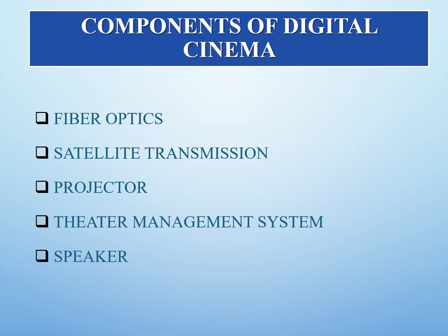Projector. Digital cinema projectors directly accept and play digital format images in high quality. DLP, digital light processing technology, is used to project images, while some of them might use LCD or some kind of modified LCD crystals for projection. Common projectors support 2K, 4K resolutions and have a brightness level in excess of 15,000 lumens. The digital cinema projector supports input or output formats according to the DCI standards. There are optional lenses to change the throw distances to adjust according to the theatre conditions.